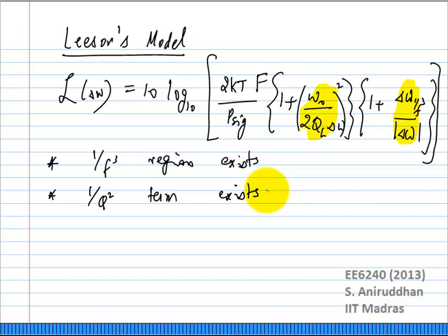Now this can mean two things. One, if you just take a VCO and try to connect something to it directly which has some input resistance, obviously several things are going to happen. For example, the amplitude of the oscillator depends on the parallel resistance of the tank. We know this. If you take a circuit which has an input resistance which is going to appear in parallel with this, the amplitude will immediately fall. Right? Number two, apart from the amplitude falling, the frequency response of the tank is going to change, so the noise response of the oscillator is also going to change. So you know both of these things.